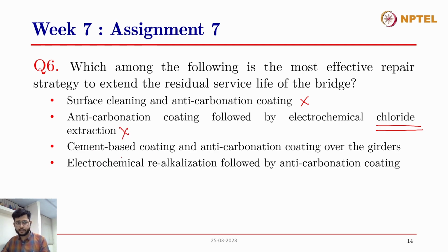The third option is cement based coating and anti-carbonation coating over the girders. Again, as we have already discussed in the first option, the carbonation front has already reached the rebar location. Applying a cement based coating now won't help, because the concrete is already carbonated, and therefore this is not the right answer to go with.